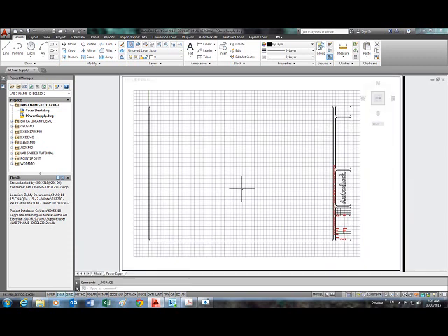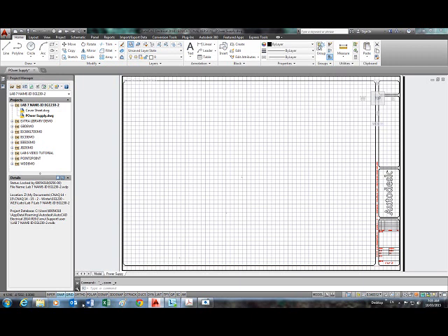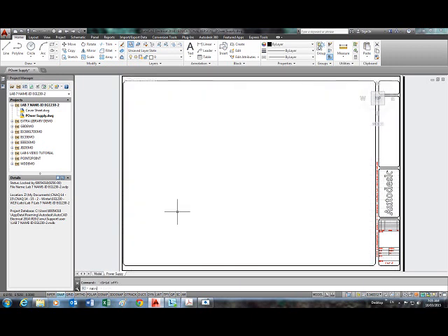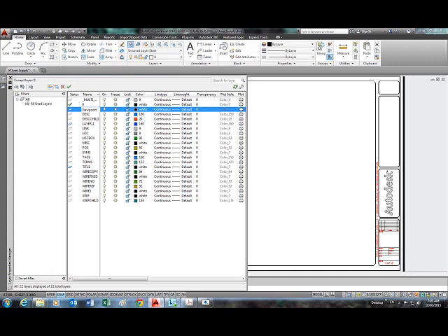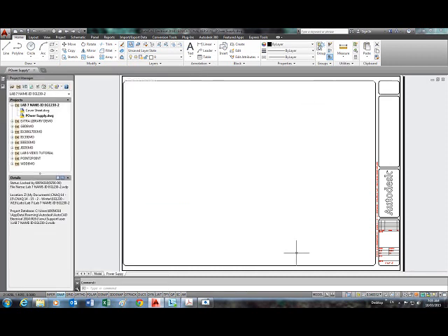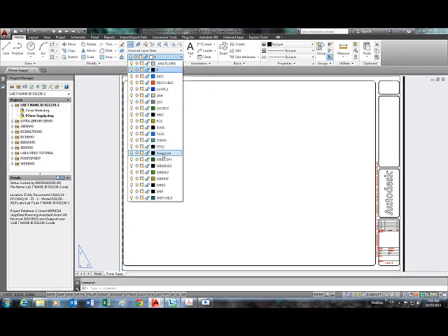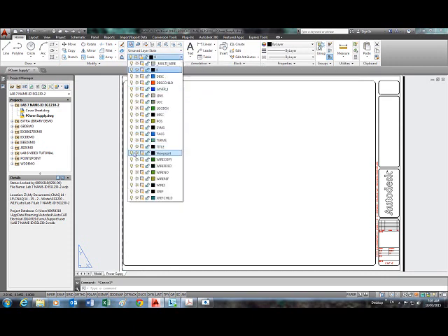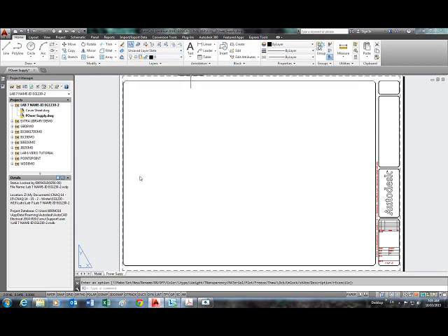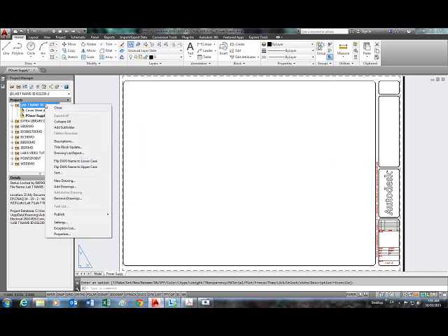Go to model space, double click the wheel, zoom extent, turn off grid, nav cube off. Let's create another layer. Viewport, and we'll move. Okay, go paper space first. Choose the viewport. Move the viewport to viewport layer, and then escape to go back to the current layer and turn off viewport so that it does not print. Okay, right click and we'll go new drawing.